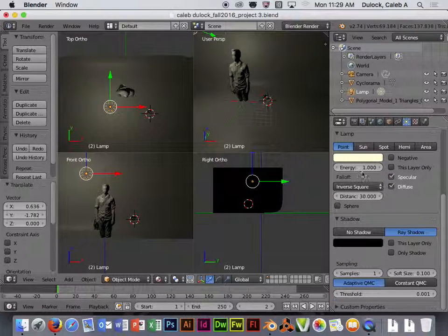The rest of the settings inside there I'm not going to really go over. Those are just the two main ones to know about inside this first section for point lighting. If you look down below the actual lamp settings, there's shadow settings. So you can tell your light to cast shadows if it's possible for the light source to cast shadows. With a hemispheric light, or a point-based light, sometimes it's a little more tricky to cast a shadow into the scene.